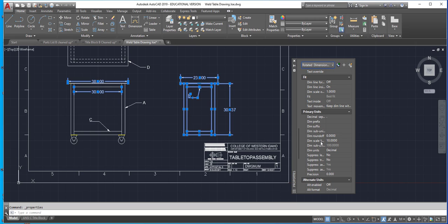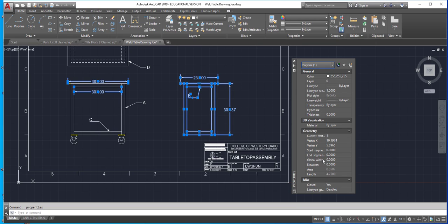As you can see, our dimension scale linear is at 10.0, and that's from where we changed it earlier the other way. The other way is a little faster and easier, I think, because you just come up and grab this and work through there. But both ways are effective. They do the same thing. Okay. This one you can get kind of wonky because, let's say there's a radius in here. Sometimes there's another radial dimension, and if you didn't click on it, that number may not change. But if you selected, highlighted, and went with the other method, everything changes. Okay, you don't have to go through this whole menu of dropping down through the 5. Okay?